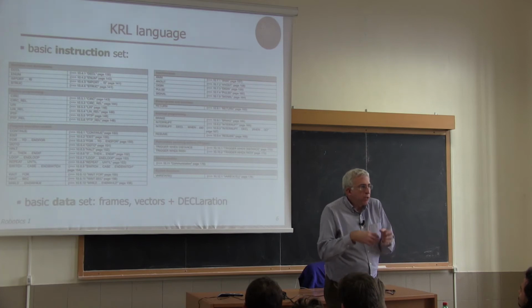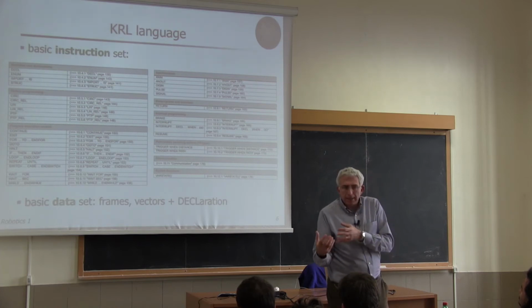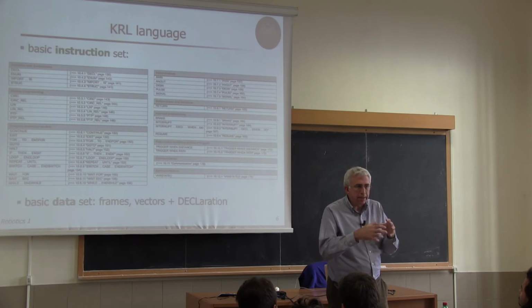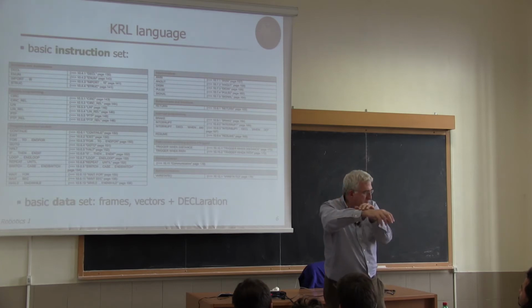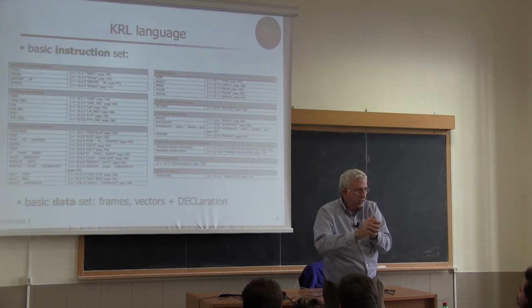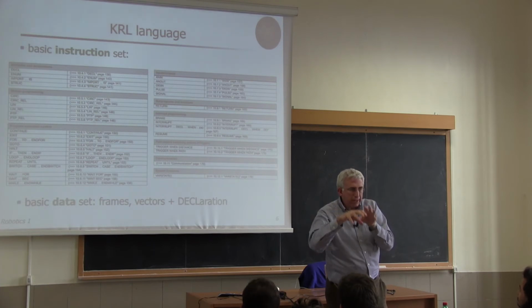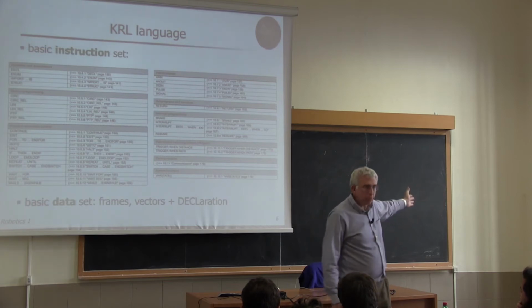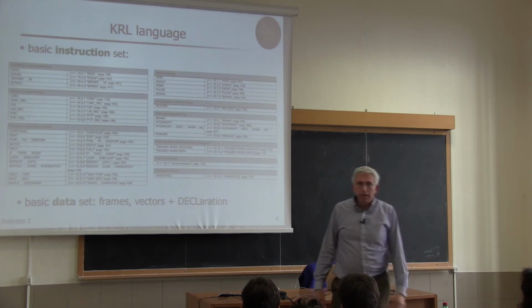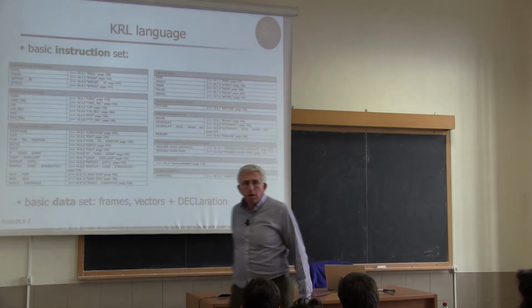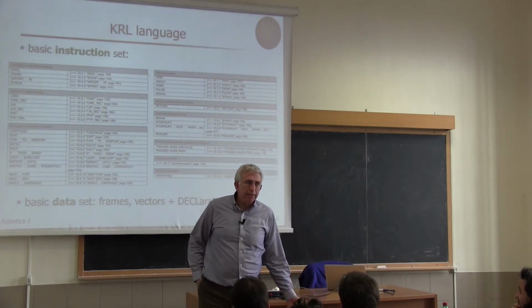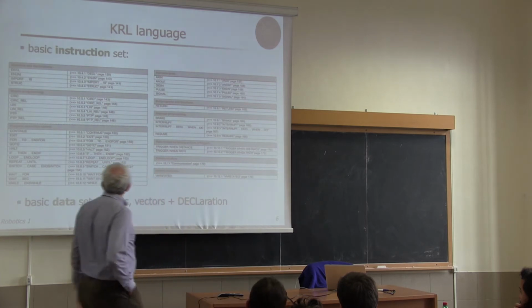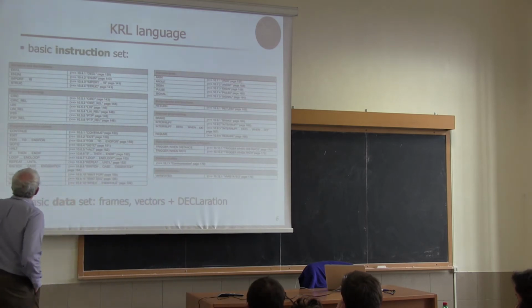But of course, you may wish to code some other task kinematics. For instance, you may be interested in some particular point in the chain, not just the end effector. So you may need to have access to the frame that describes the relative position of the link and stop at a certain point, just like we have done with the chain of homogeneous transformations in the Denavit-Hartenberg convention. Okay.